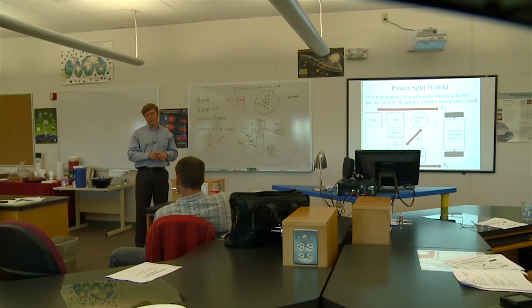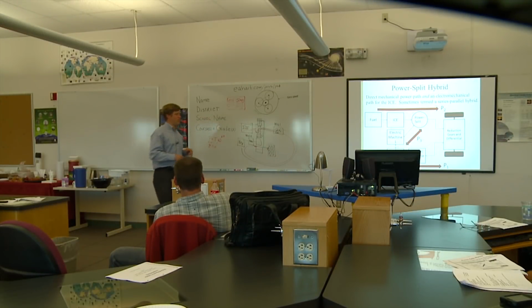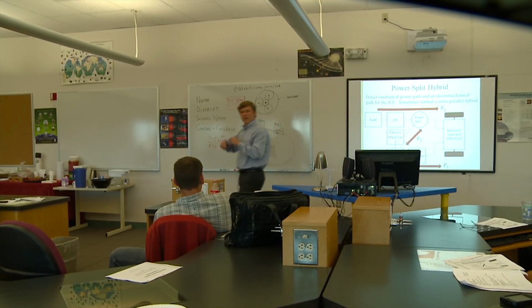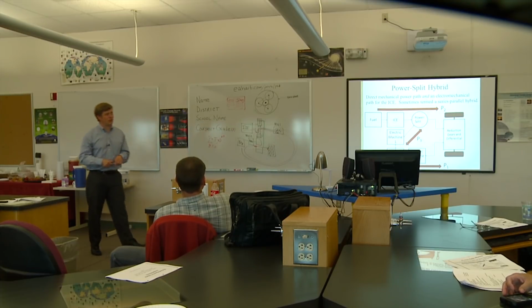And so the original generation of that had a power split that looks exactly like this in the front, and an all-electric drivetrain in the rear, so an electric motor that turned the rear wheels. Now, my understanding was that in the most recent generation, whether that's post 2009 or 2010 or something like that, they'd gone back to having a traditional transfer case for whatever reason. But it's still an all-wheel drive system. So it's got this sort of system, but then the gears and differential would also have a transfer case going to the back with a coupling.